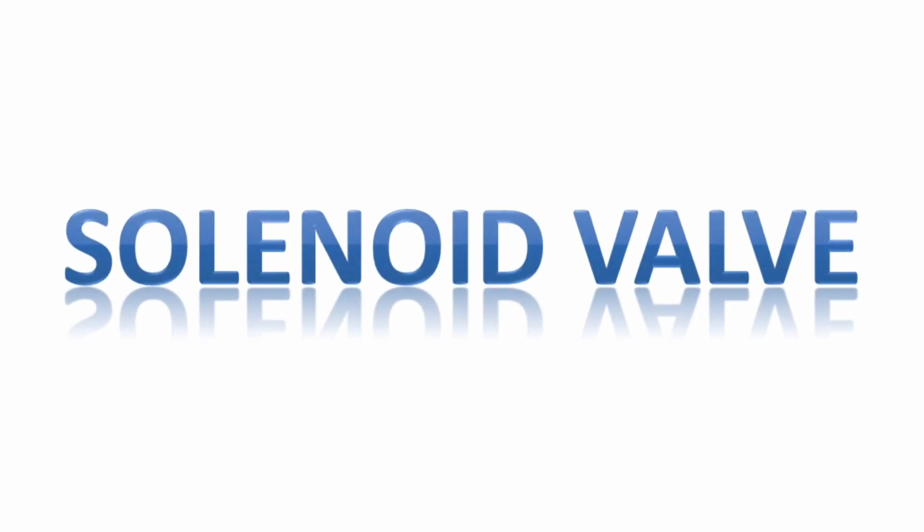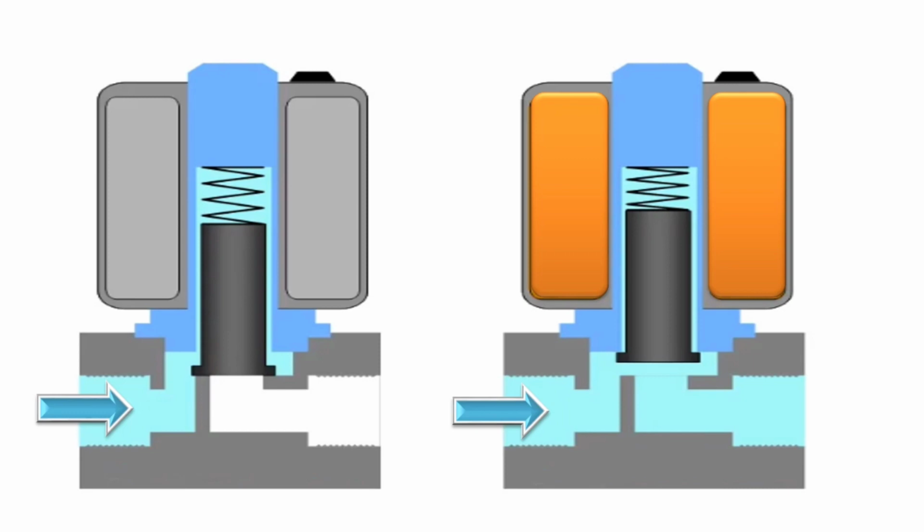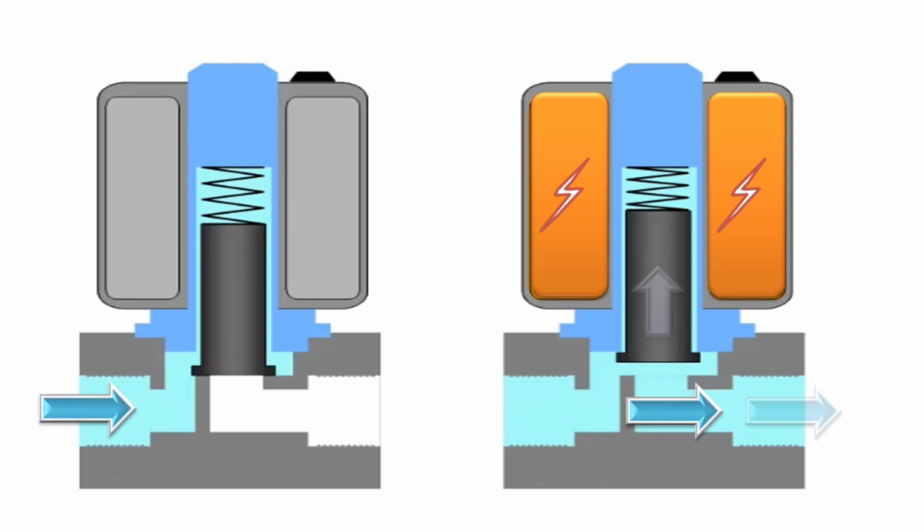The solenoid valves are control units which in normal condition block the supply of the refrigerant to the evaporator coil, as you can see in the diagram. When this solenoid valve is electrically energized, it will allow fluid flow. The actuator takes the form of an electromagnet. When energized, a magnetic field builds up which pulls a plunger or pivoted armature against the action of the spring. This will cause the flow of refrigerant fluid in the system.